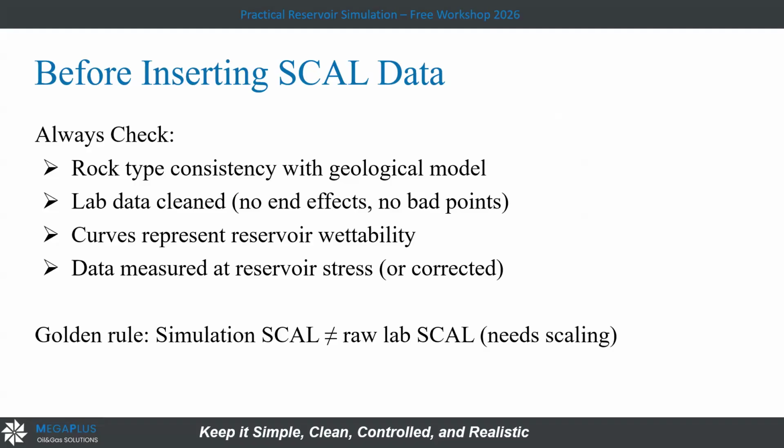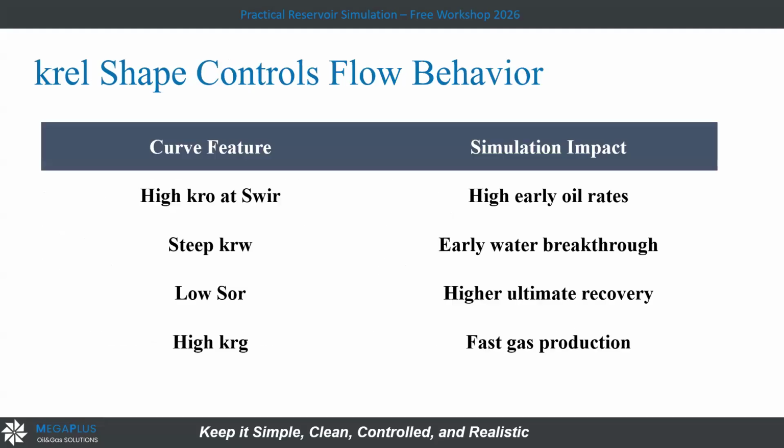Curves must represent reservoir wettability, and that's what wettability is, the angle, and it depends on the interfacial tension forces that I told you about. The data must be measured in the lab at the same stress and the same pressure as the reservoir. And I need to mention the simulation scale, not the raw lab scale. You have a homework you have to do before inserting the data in the simulation.